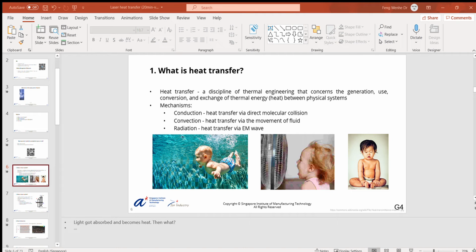All right, I'm not sure if the equation reminds you of anything, so probably you have all heard about or learned about Ohm's law, in which the current is defined as the difference of voltage divided by resistance. And in this model, the heat transfer rate has the same form. So if you combine a few items together, the overall heat transfer rate is just the temperature difference at two sides of this object divided by the overall thermal resistance. So I assume that something very important is missing in the picture. What is it?